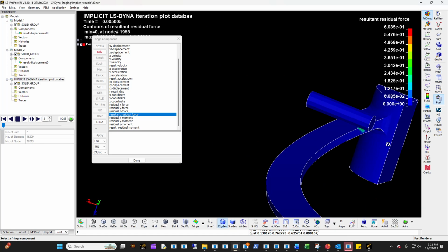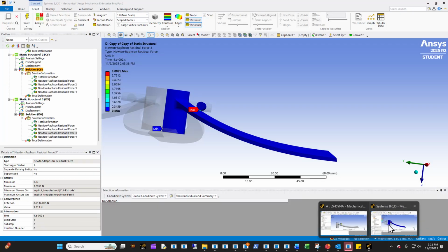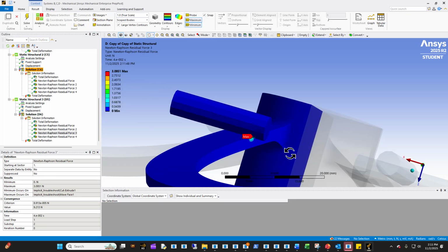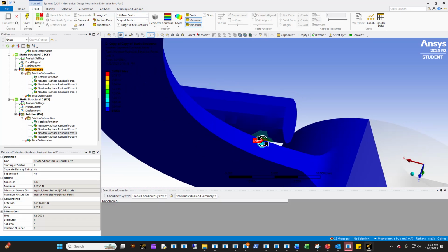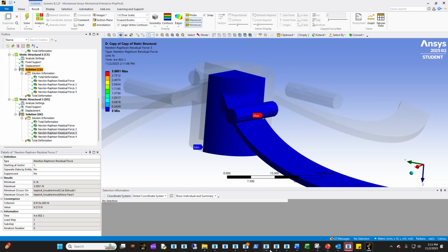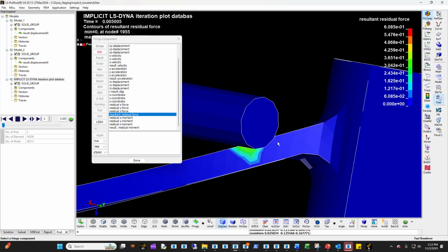But you can sort of see this is exactly the same thing as you will see inside ANSYS Mechanical if you're familiar with the product, which is that you get to see this type of problem right here. You see that? It's exactly the same type of information that you're getting from here. And that tells you that this is a very good way to troubleshoot, right? So this tells me my problem for convergence here is due to that contact pair.